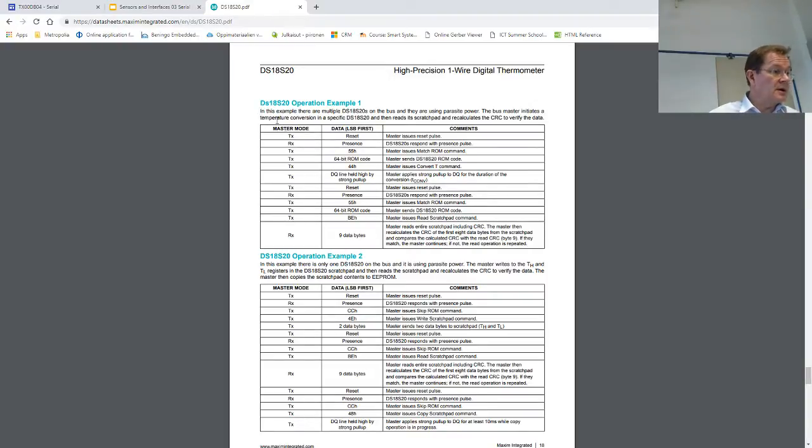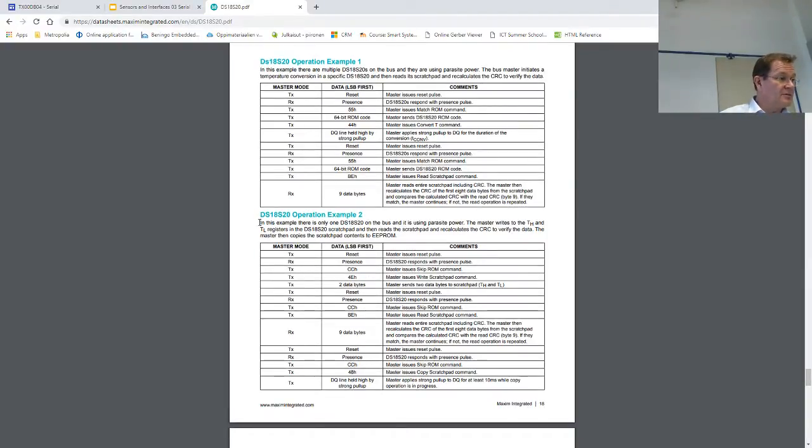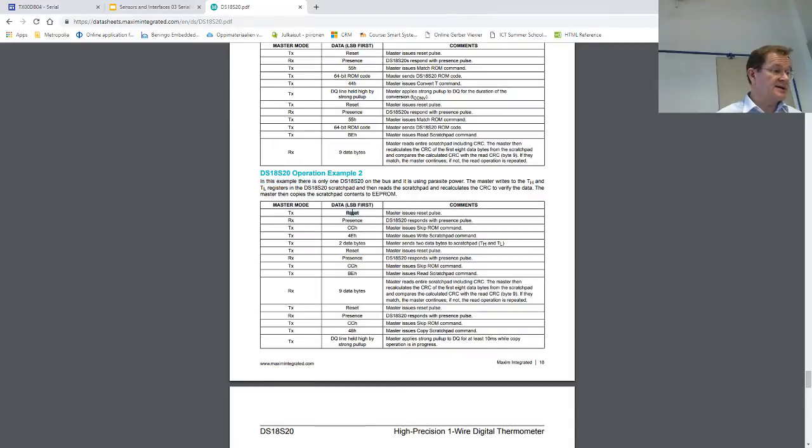So, okay, maybe that other one. Only one device is connected, and basically this is what you would be doing first. First is your reset, and then to check the presence, meaning that you just take a look at the register from your one-wire module. Was there something online?